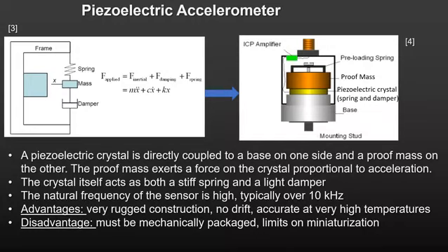The piezoelectric accelerometer has a very rugged construction. No drift, and with no internal electrical resistance to worry about, it can be used at high temperatures. When it was first invented, people liked its small size, but with today's miniaturized electronics, the package size is considered large.